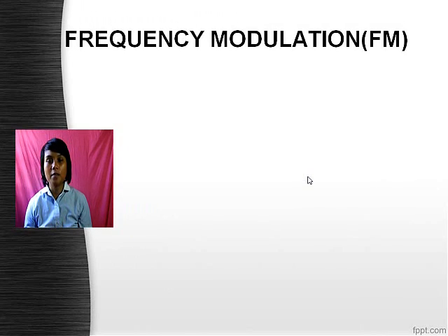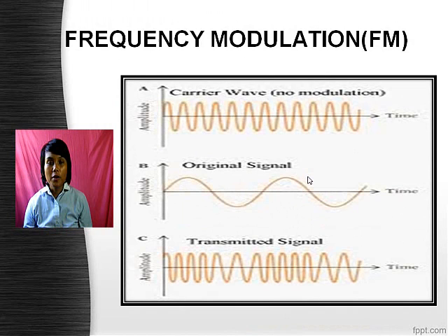Next, you can see the diagram of frequency modulation. FM radio frequencies are given in megahertz, and the number on your FM dial represents the frequency in megahertz of the carrier wave before it's modulated. Broadcasting at 100 megahertz requires an antenna 0.75 meter long, and the length of this antenna must be adjustable to produce varying frequencies. The original signal for an FM transmission will typically have a bandwidth of 15 kHz. The bandwidth of the transmitted signal will be much larger, typically around 200 kHz, since the frequency changes so much.